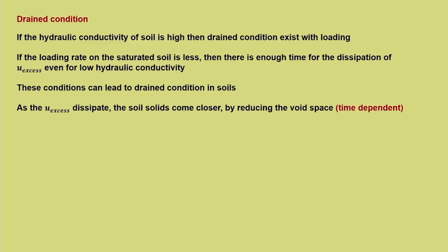When the water moves out, the voids will try to come closer, and the packing is better. So, whatever stress the water has carried before dissipating will get transferred to the soil solids along their points of contact, and that is what is intergranular stress. Any loss in pore water pressure is a gain in intergranular or effective stress. So, it comes closer by reducing the void space. Now, this is a very important aspect. Such a process is time dependent.